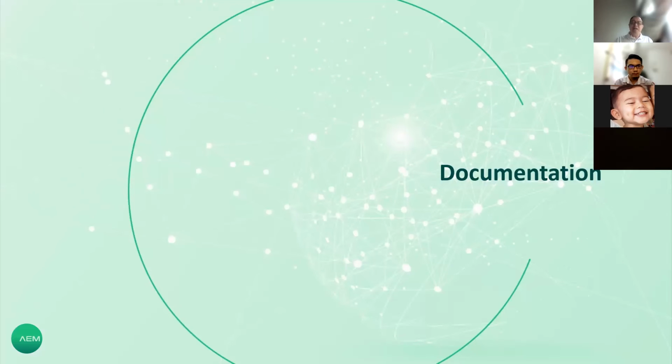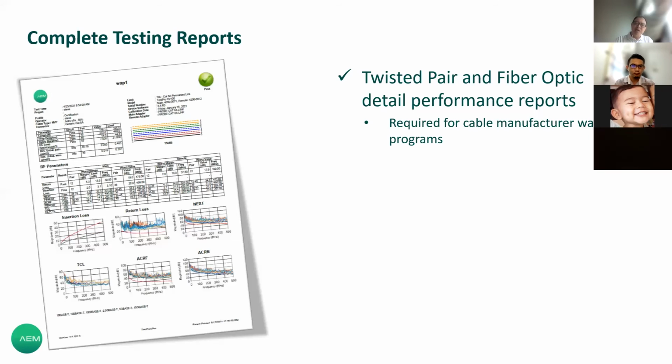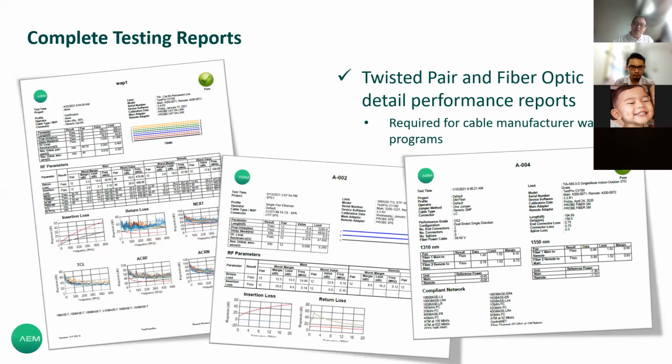At the end of all testing, you need a report, you need documentation, to show your client, your boss, your team that all these cables are not just tested on the physical layer, but also measured for multigig and for power at the same time. This report is critical. In case something goes wrong with a certain link in the future, you can refer back to the documentation to see if it measures the same as your previous report.